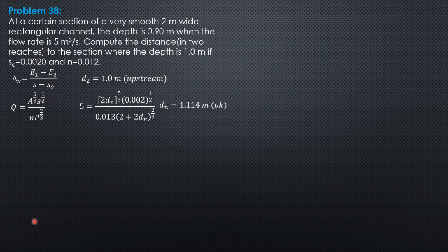So this does not cross this range of depths from 0.9 to 1.0. It's outside. So okay. Then the critical depth, cube root of q squared over g, where q is capital Q over width 2 meters, over g 9.81. So it is equal to 0.8605 meters. This is the critical depth, 0.8605. So it does not cross also the range 0.9 to 1 meter.